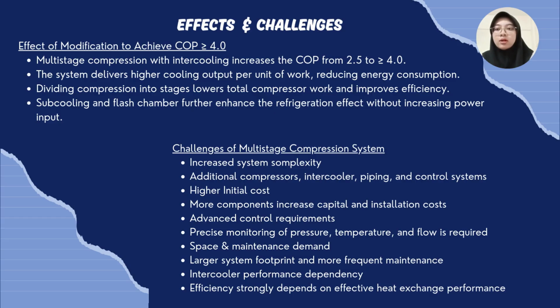Challenge of multi-stage compression system. Increased system complexity: additional compressor, intercooler, piping and control system. Higher initial cost: more components, increased capital and installation costs. Advanced control requirement: precise monitoring of pressure, temperature and flow is required. Space and maintenance demand: large system footprint and more frequent maintenance. Intercooler performance dependency: efficiency strongly depends on effective heat exchange performance.